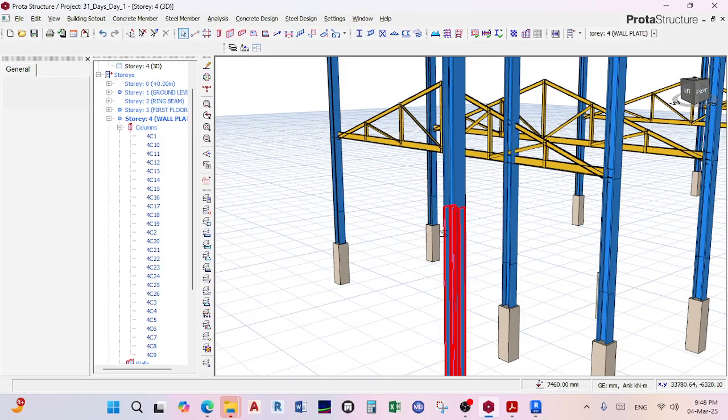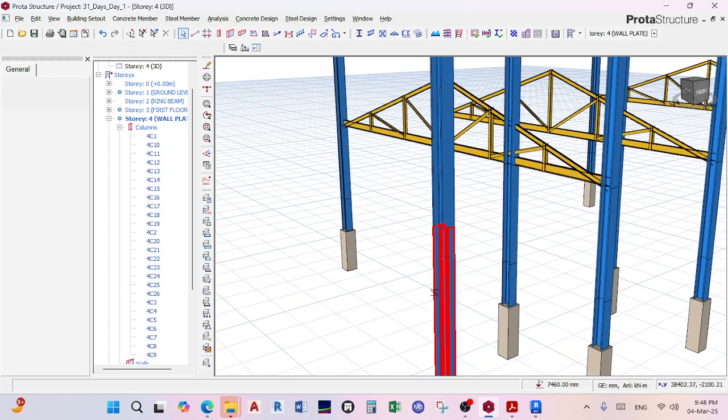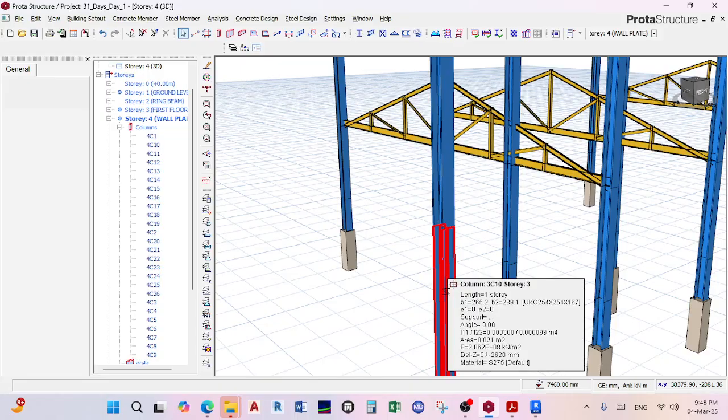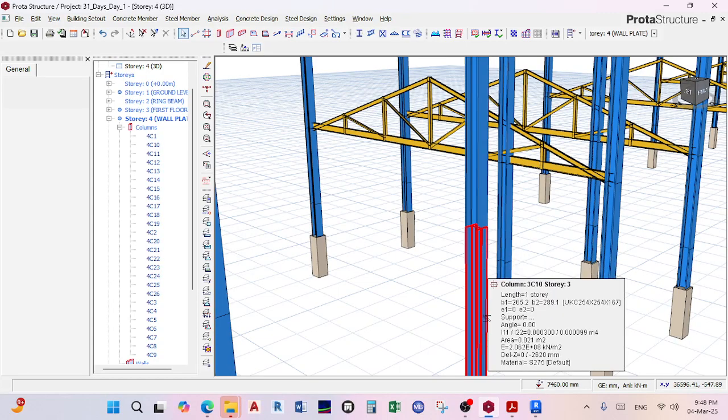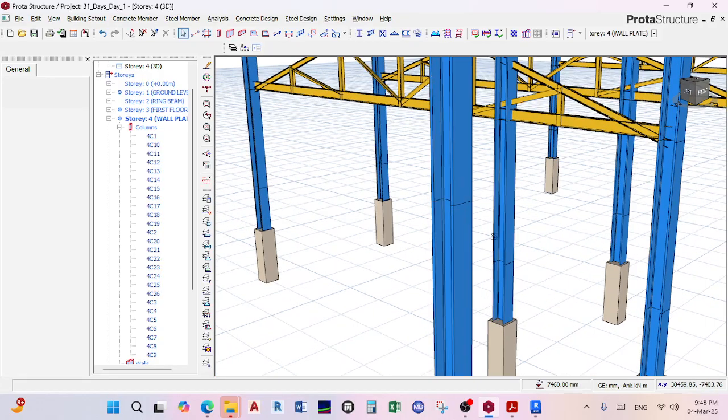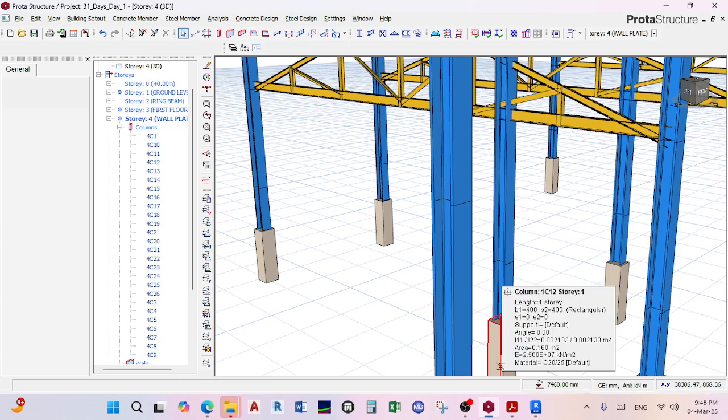For concrete, this is acceptable because you would have left starter bars, and I know Paul knows this concept a lot because we worked together at King's Hospital, and he was part of the people that were surveying. If you've done one floor and you want to do another floor, you leave starter bars so that the shutter board can come and cover and you can pour concrete again. For concrete, it's acceptable. For steel, you'd have to weld and you have a weak point. And there's no point in cutting it in 4 meters, 4 meters when you can buy 13 and just put the whole 13 meters. So when you're modeling, these are some of the things that you need to factor. For concrete, it's okay. For steel, it's not.